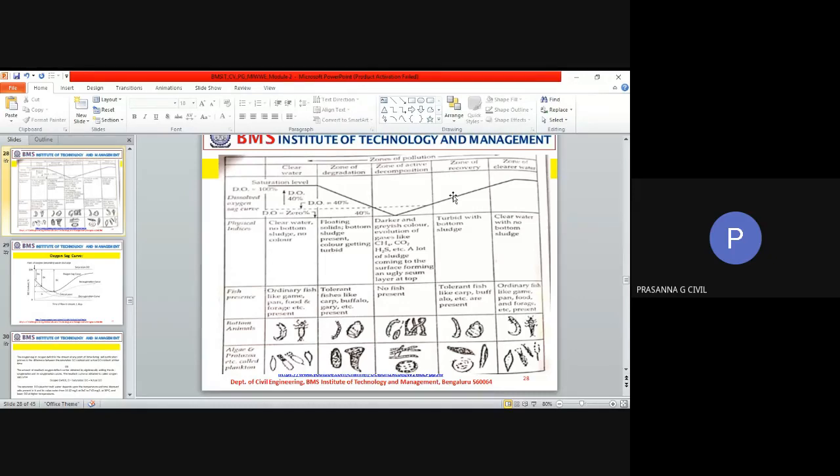And you know what are the responsible things for giving out oxygen to water? Your algae, phytoplankton, etc. In the daytime, they will give out oxygen. Understood? And even as the river flows, when the pollutant contaminant is less, the currents and everything present in the water will allow DO to dissolve. And since the organics have been decomposed here, they are not getting used up once again. And that is allowing for this recovery to happen.